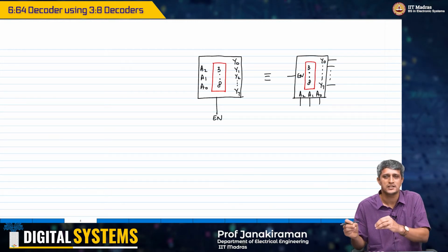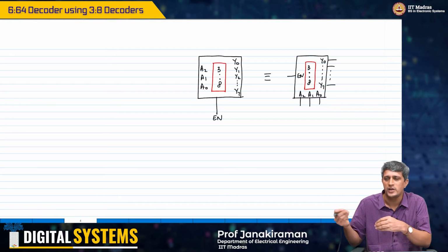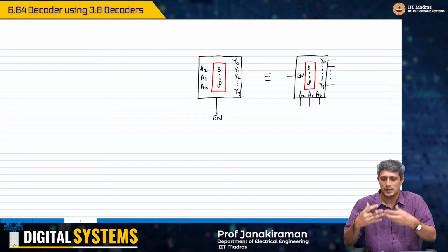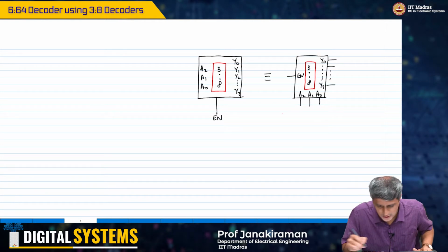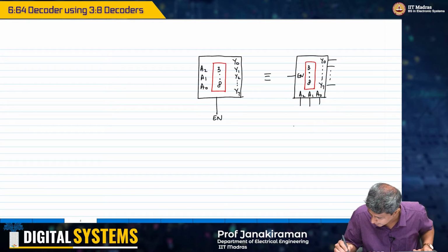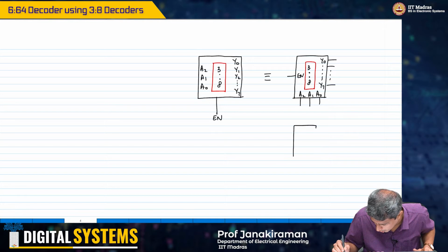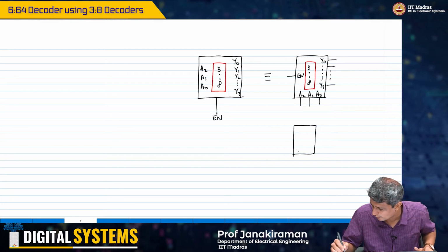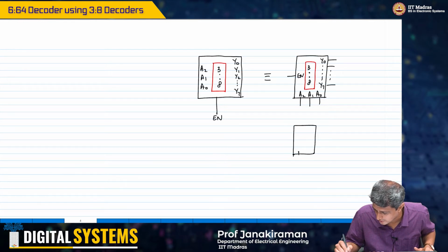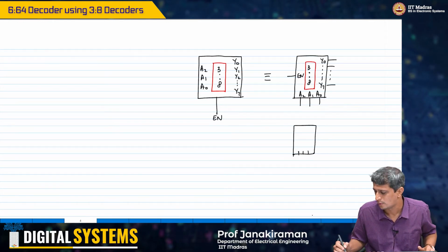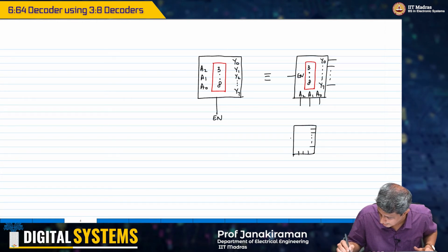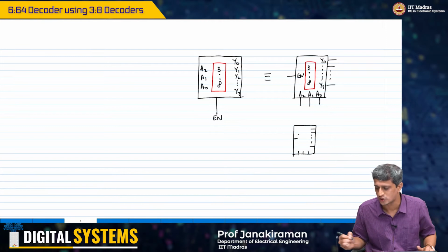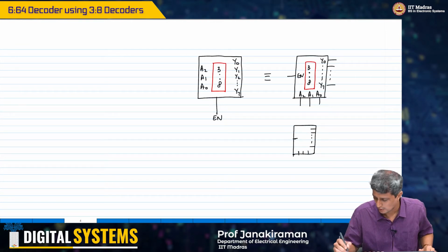That is going to be placed as per our convenience of drawing the schematic or drawing the logic diagram that we will see now. Okay, so instead of writing this internal block of A0, A1, A2, and Y0, Y2, Y7 and all that, I will just put 3 pins here and 8 pins here, and 1 pin here, which is called the enable.